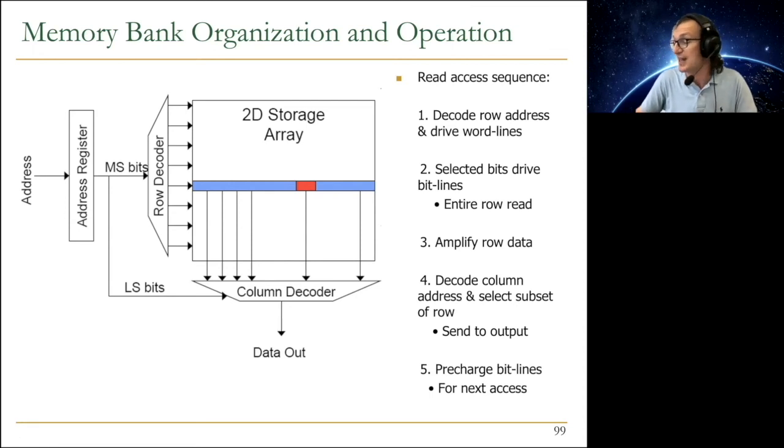It depends, basically. It depends on the DRAM chip. It depends on the SRAM. So in DRAM chips, it could be 1 byte, it could be 16 bits, it could be 32 bits, it could be 4 bits also. There are some DRAM chips that are that way. But in SRAM, it could be actually much wider, because in SRAM, you normally put SRAM on chip. And on chip, you don't have a pin bandwidth, pin count problem.